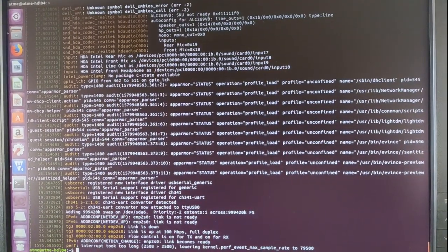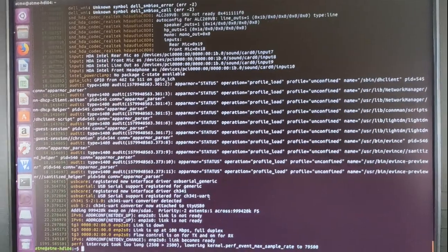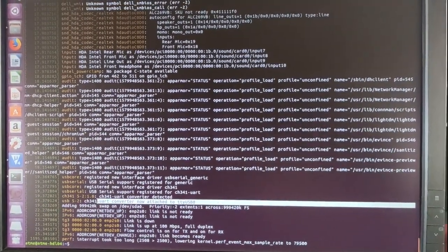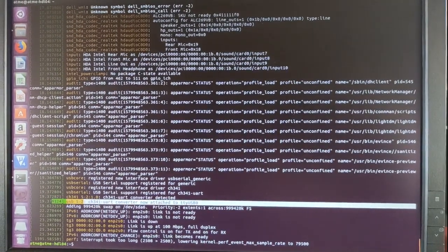I hope you understood the program flow of the external interrupt. Now I'll show you how to download the program, the hex file, into the hardware and how to execute it. Let us look at the demonstration. As we did in the previous example, the first command you need to type to get the hardware information is dmesg. You can observe that UART is connected to ttyUSB0. This is a device ID generated by the system.